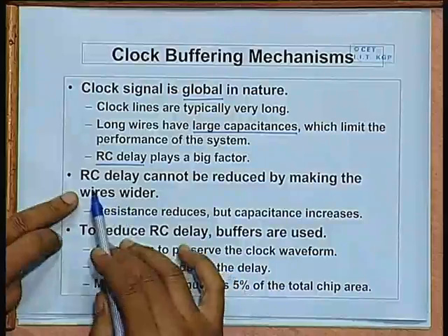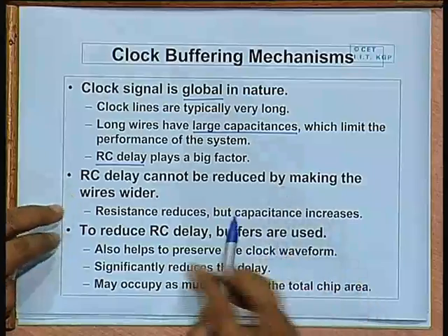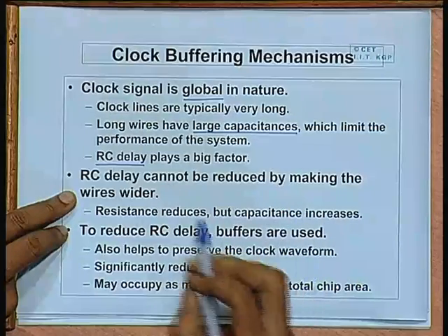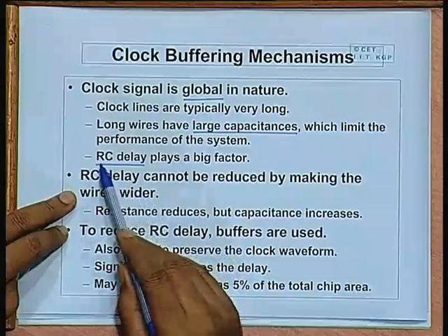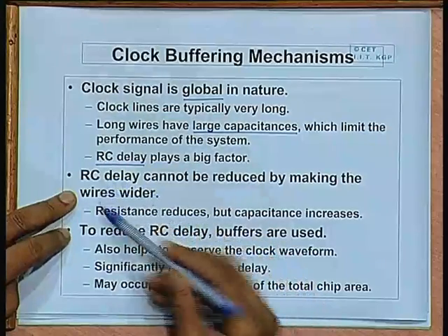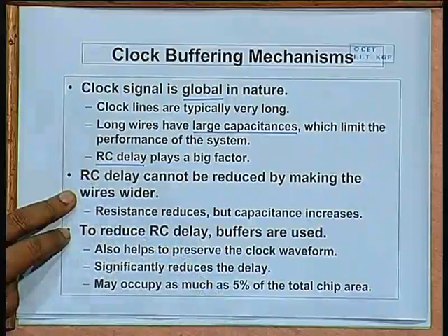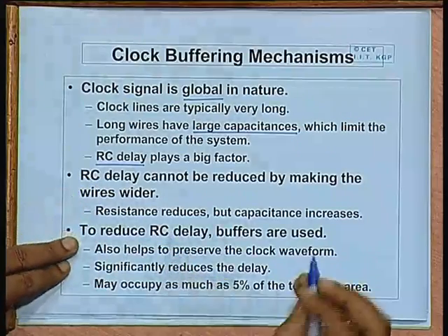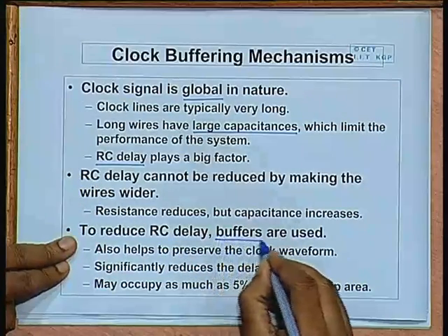And one issue is that you cannot reduce the RC delay simply by making the wires wider, because if you make the wires wider, R will decrease, but C will increase. So, by making the wires thinner or thicker, you really cannot change the RC delay appreciably. To reduce the RC delay, buffers are used. This is one point